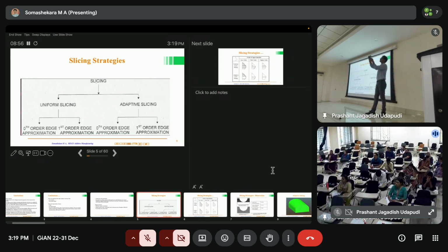But when I go to the top, why should I only deposit in this direction? Why don't I deposit like this, and then like this? And then can I cut this area and prepare slices only for this area, which is called adaptive slicing.